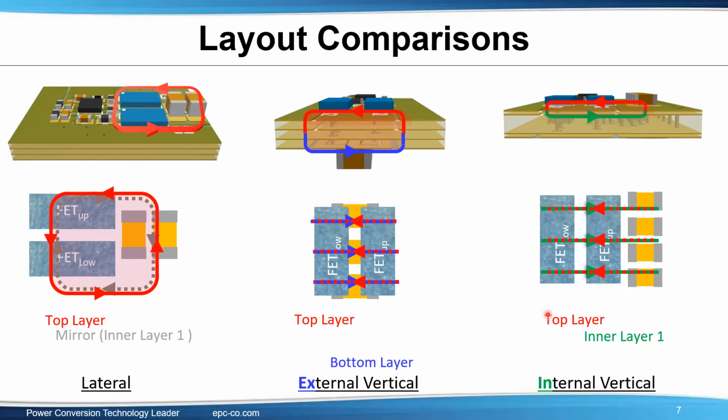What would be the impact of putting the gate driver on the opposite layer from the FET? I'm doing this. It's not forbidden. It really depends on how fast you're driving your converter. Are we talking about a 2 megahertz converter with a 25 volt per nanosecond switching node? Or a 100 kilohertz inverter for a motor with a 6 volt per nanosecond switching node?